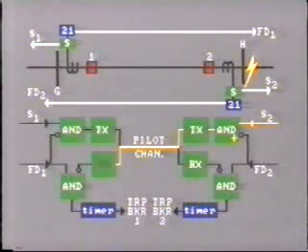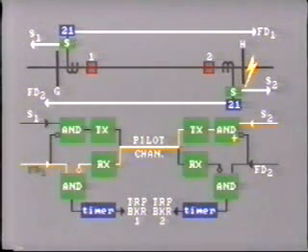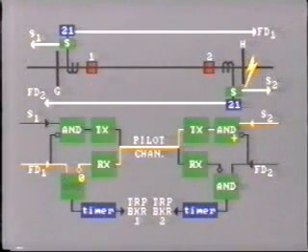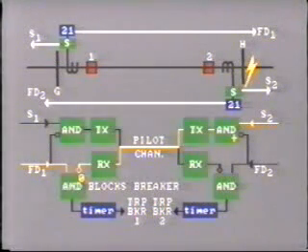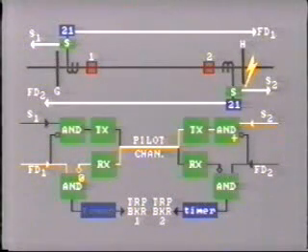This is received at the other end, station G, and the signal is passed into the permissive tripping circuit and mixed with the signal from fault detector 1, which, as you remember, is trying to trip breaker 1. The positive input signal from the receiver becomes a 0 signal. As this logic box shows AND, it needs 2 positive input signals, one from the fault detector and one from the receiver. But at this moment it has only one, that from the fault detector. So the breaker is blocked from tripping by the transmitted signal. To give time for signal transmission and logic circuit operation, the tripping circuit is fitted with a timer. So for this external fault, no tripping would take place.